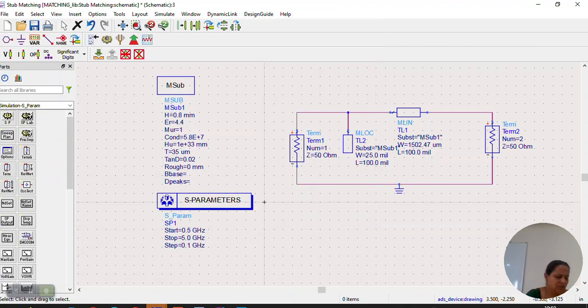Here I will change it to micrometer. L was 3971.85. You have to note down all these values so that you can enter them later, in micrometer. And then W is the same thing, because width will not change, only the length will change.